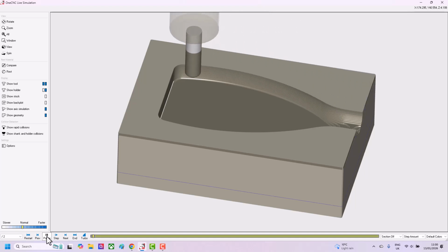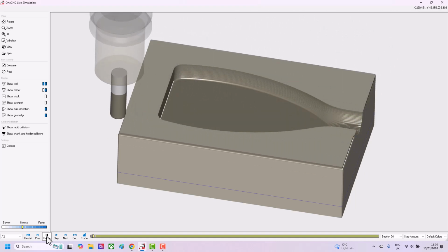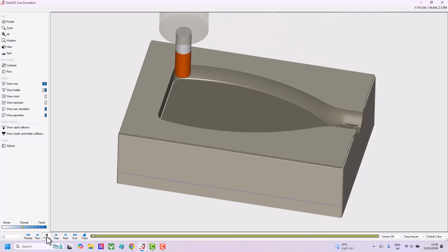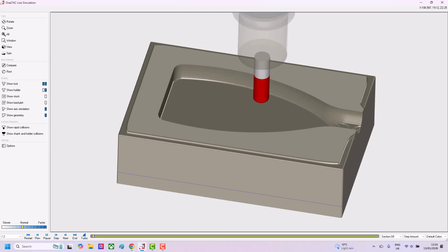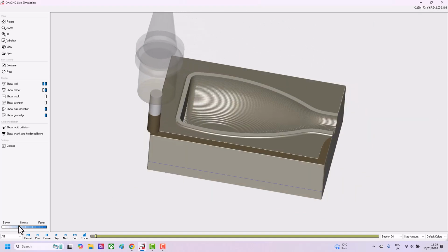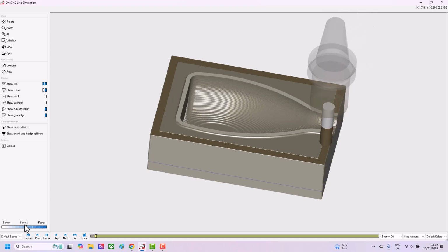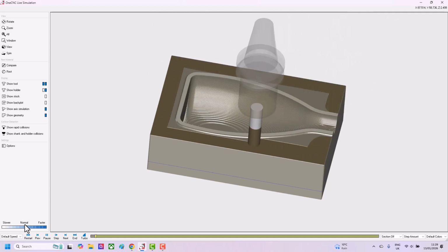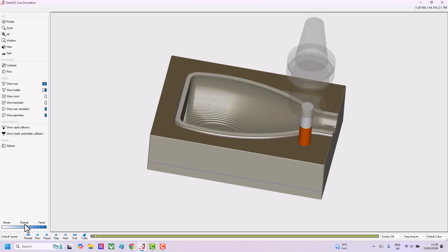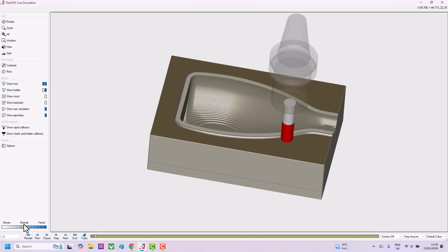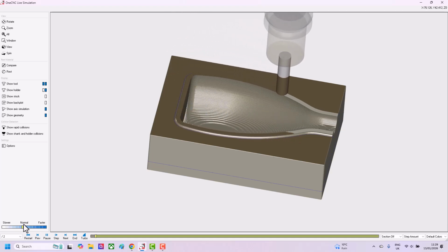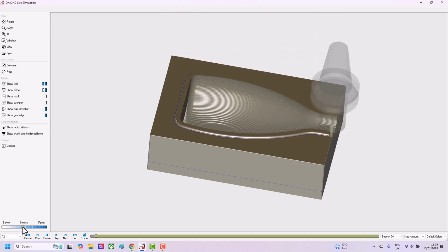And because obviously we've used the extent boundary, it's going to rough machine the flat area on the top as well. So the initial first pass on the flat area machining, just doing the large plateau. As I say, these toolpaths you will be familiar with. Finally coming in and machining off the top face. And here comes the pencil trace. As I say, this is a size for size radius scenario.